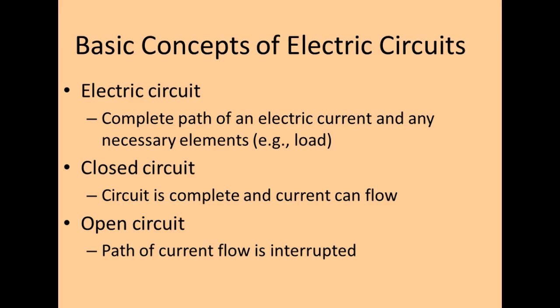And a second power source that I'll title L2, line 2, the bus bar. That's just a conductor that we can get the power from. And it's also 115 volts AC. All right? And if you took your meter and you read across it, that would read 230. If you read from one item to ground, it would read 115.